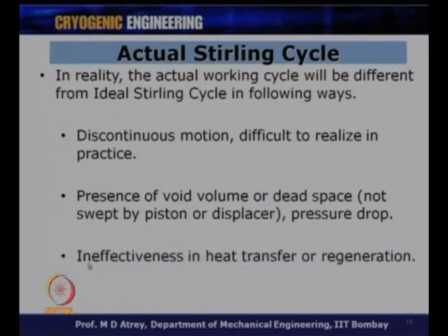Also, we talked about having heat exchange between the regenerator matrix and the gas, and this heat exchange may not be perfect, and therefore, we will have some ineffectiveness associated with this heat exchange. So, this is a very important thing which has to be considered while designing actual Stirling cycle. So, we will have ineffectiveness in heat transfer or regeneration. Is the gas transferring all the heat to the regenerator? Is the gas taking all the heat from the regenerator? It will all depend upon how effective this regenerator is, and therefore, we will have to consider the effectiveness of heat exchange during this actual Stirling cycle.